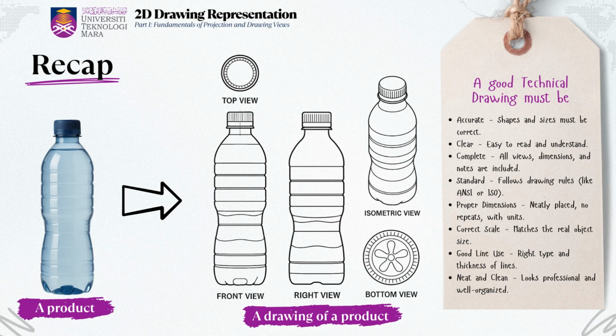Let's take a moment to revisit what we've learned so far before moving on. On this slide, you can see how a real-life product, in this case, a plastic bottle, is represented using technical drawings. On the left, we have the actual product. On the right, we see multiple technical views of that same bottle, the front view, right view, top view, bottom view, and even an isometric view, which gives us a 3D-like representation. Each of these views is carefully constructed to show different sides of the object with accurate proportions and detail. This is the foundation of what technical drawing is all about, translating real-world objects into standardized 2D views that anyone in engineering, manufacturing, or design can interpret correctly.